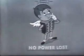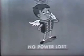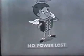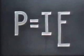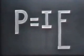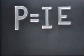Now, if it were possible to construct a perfect transformer, there would be no loss in power in the transformer. Power would be transferred from one voltage current level to another. Since power is the product of current times voltage, an increase in voltage by means of the transformer must result in a decrease in current. And likewise, a decrease in voltage by the transformer must result in an increase in current.